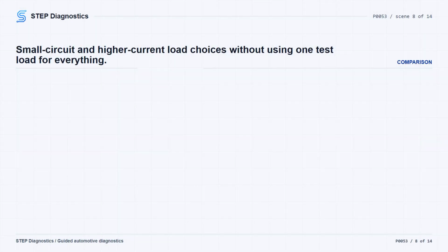When the diagnosis turns into electrical testing, match the load to the circuit. Circuits carrying approximately 200-1000 mA may be loaded with a 250-350 ohm test light. Conductor sizes 24 gauge, 0.5 mm, or smaller are generally used to carry approximately 1000 mA, 1 ampere, or less, and use of a 250-350 ohm test light to load these circuits is appropriate. Circuits carrying more than 1 ampere should be loaded with a device requiring similar current, for example a brake light bulb. Conductor sizes 20 gauge, 0.8 mm, or larger are generally used to carry 1 ampere, 1000 mA or more.